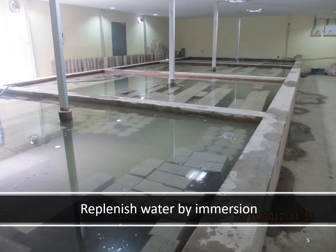With the higher temperature, even if you are not testing the 1 day strength, when you test the 28-day strength, it will be less than the average strength you normally get when cured at a temperature of 27 plus minus 2. So it is important to make sure that the curing water temperature in the curing tank is maintained at 27 plus minus 2 at all points of time, because this is the result which is indicative in order to accept or reject a material.